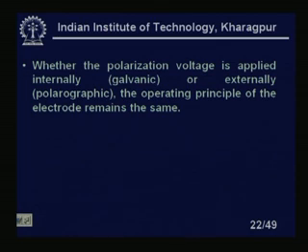Whether the polarization voltage is applied internally, in the case of galvanic, or externally, as in the polarographic, the operating principle of the electrode remains the same. Okay. Operating principle same, whether galvanic or polarographic: in the polarographic case we give it externally, and in the galvanic case it is generated internally.